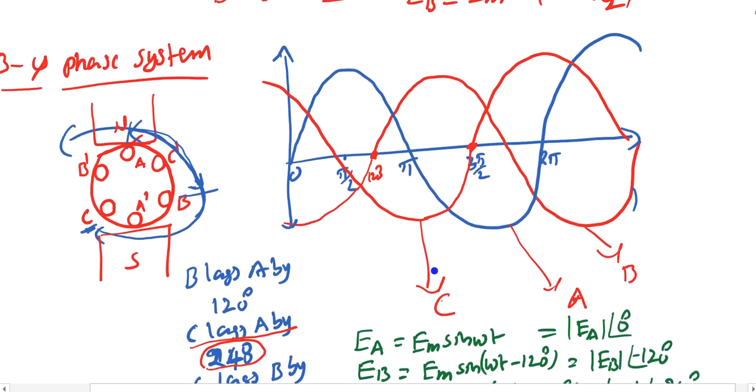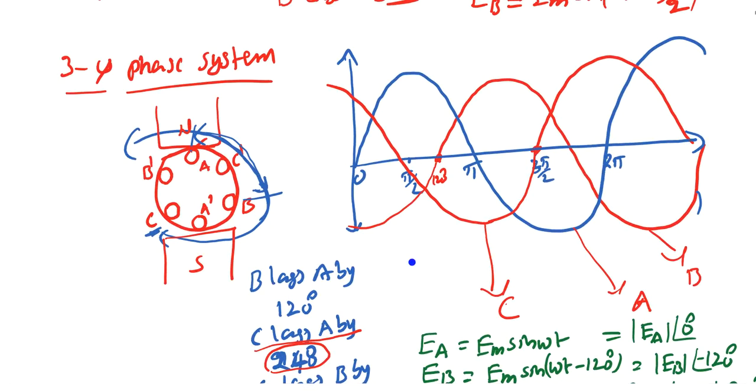If you observe the three-phase system, there is some beauty in it. Suppose any two phases are intersecting; at this moment one of the phases is at a maximum value. It may be positive or negative, but it is at a maximum value. Whenever two phases intersect, one of the phases is at a maximum, negative or positive.